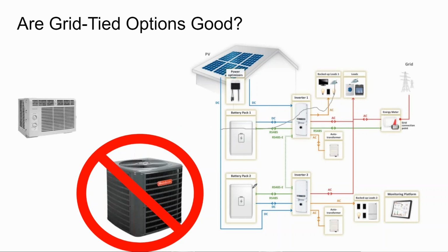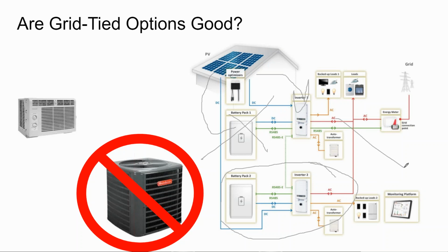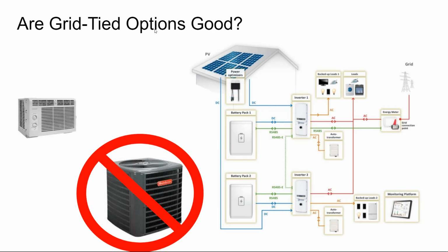On top of that, depending on how you wire the system, whether you're wiring the solar array directly into the batteries or having one battery inverter right next to a non-battery inverter, it might be that when the power goes out, you only have the battery, but the solar array goes out too, depending on how you wire it, depending on your material selection, product selection.